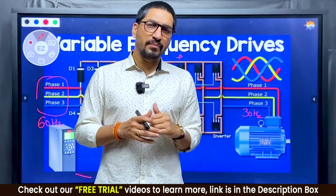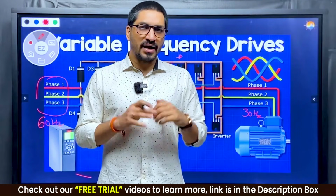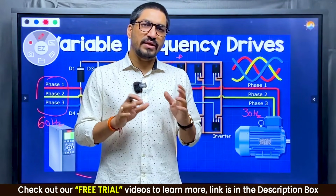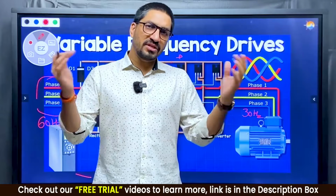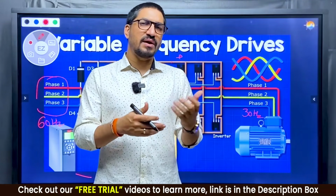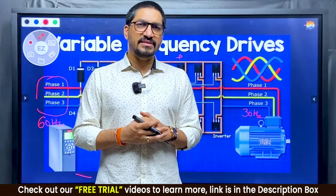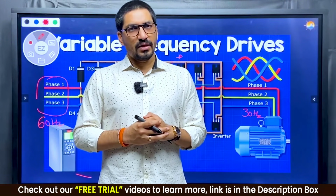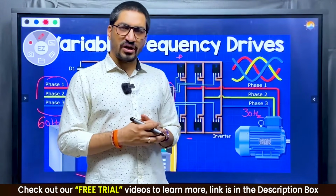Earlier we used to stop the blowers when not required. Nowadays, using VFD, we can reduce the RPM of these blowers so that less air is introduced into the engine room. Okay, so these are a few examples. There are many more such examples coming these days. Just for energy saving, we are employing those. Okay, so this is all about VFD, gentlemen.